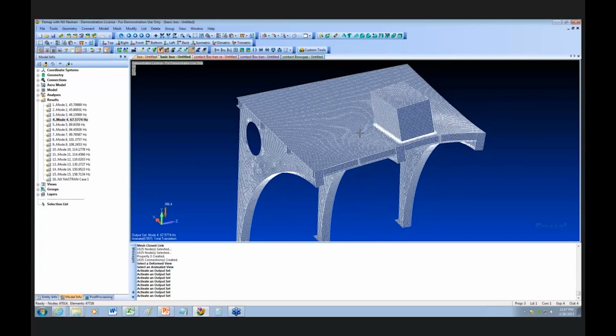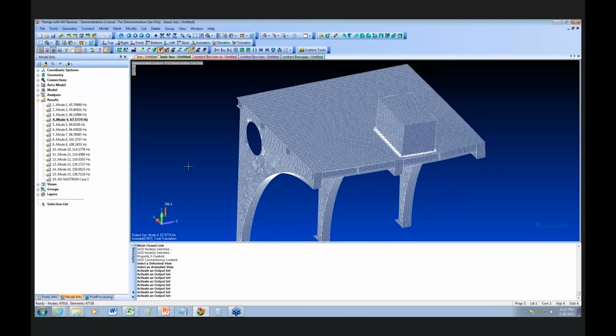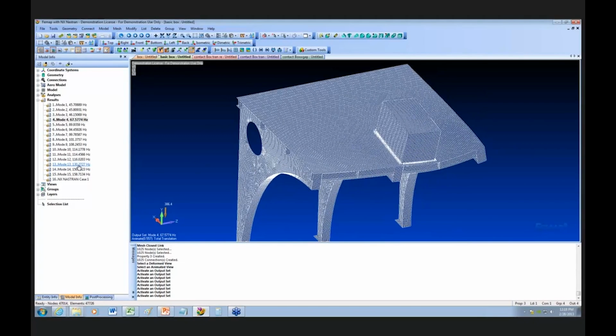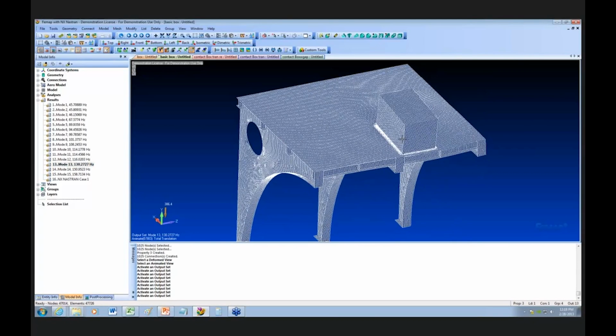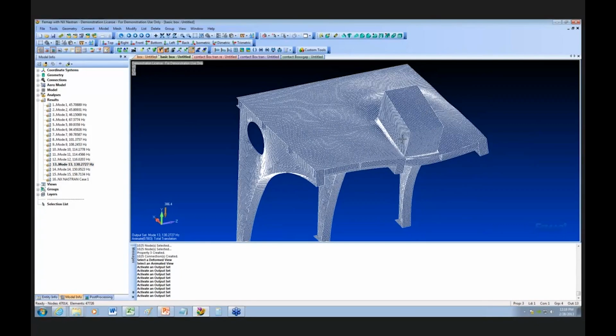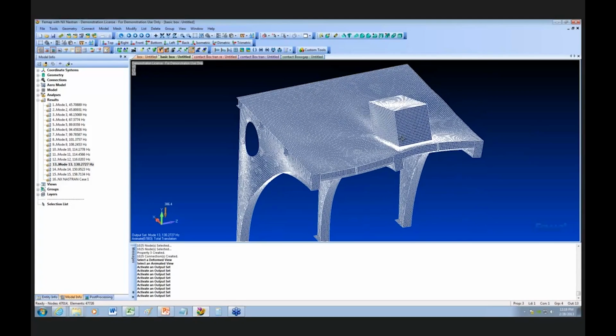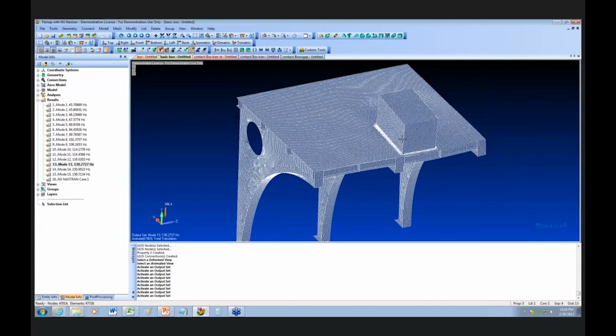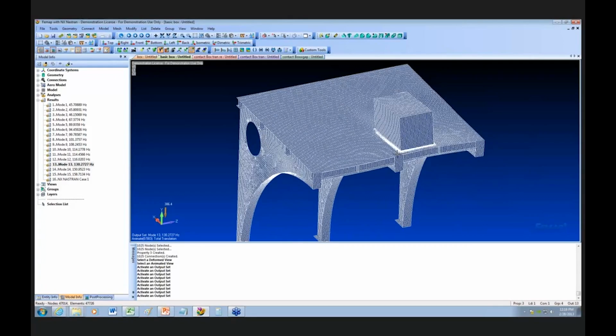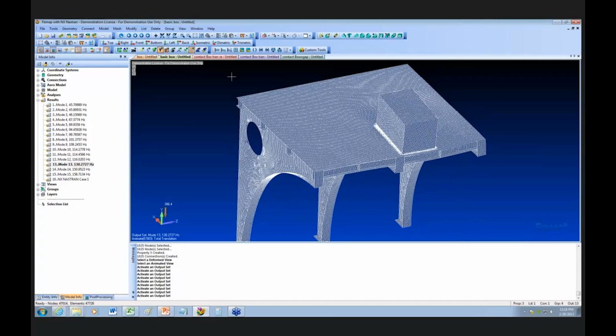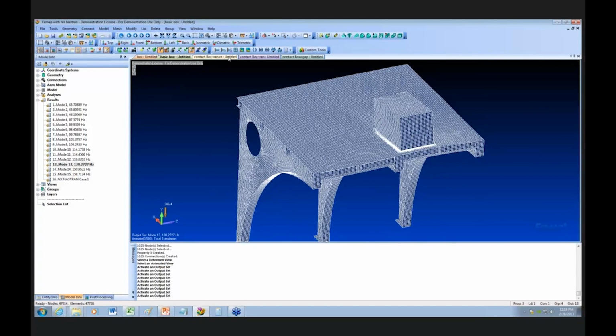Actually, this one, as it's ringing out, is not ringing out in this mode shape. I start seeing something at about 130, 135 hertz. I came down here and looked at that, and this is the mode shape where it's actually ringing out. If I was going to do this again, I would change my damping to probably 130 hertz, to take the energy out in this mode shape, because that's where the energy is actually going, or most of it is. So that's how you select the modes, and I'll show you what I did with that information as we move on to